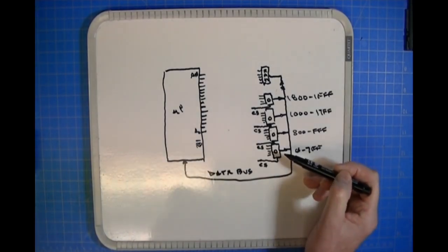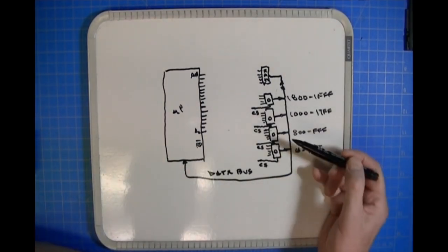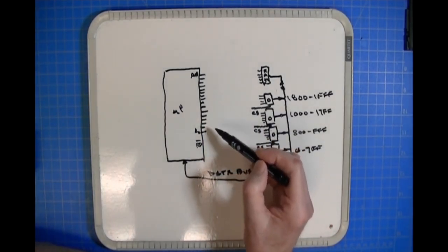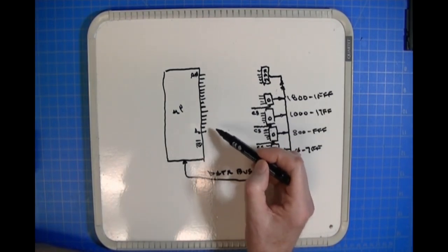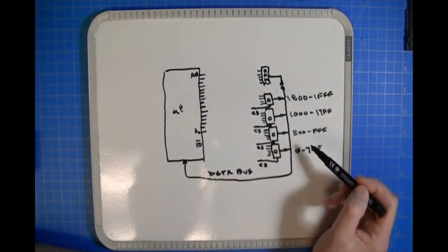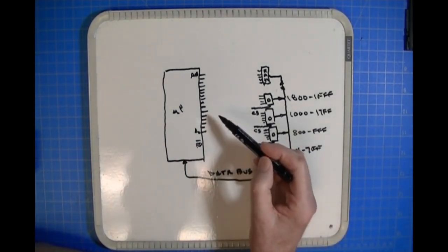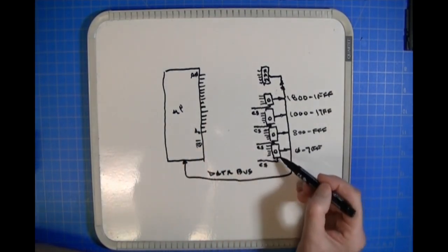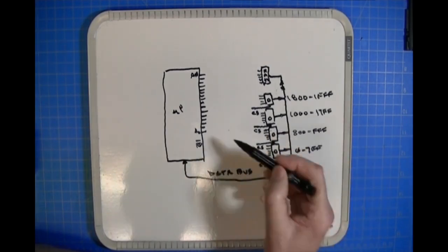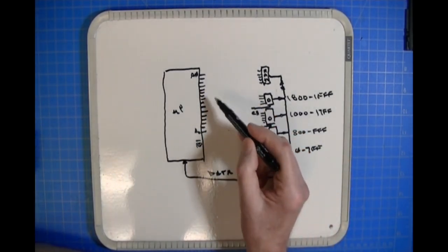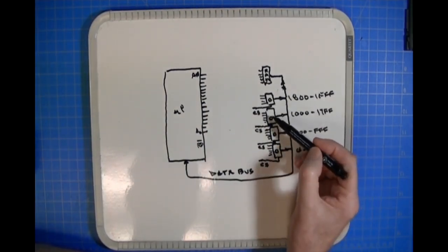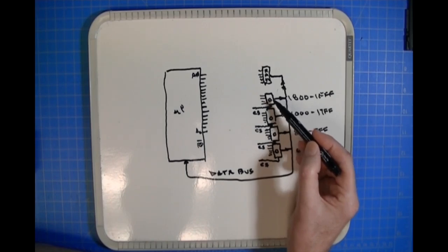Well, what happens as the program executes and the address outputs begin to increase? The last one is 7FF, and then the next one, you increment by 1, it's going to be 800. So you don't want this EPROM to be accessed, you want this EPROM to be accessed. So you've got to have decoding circuitry that will deselect this EPROM, select this EPROM, and also deselect the other EPROMs.